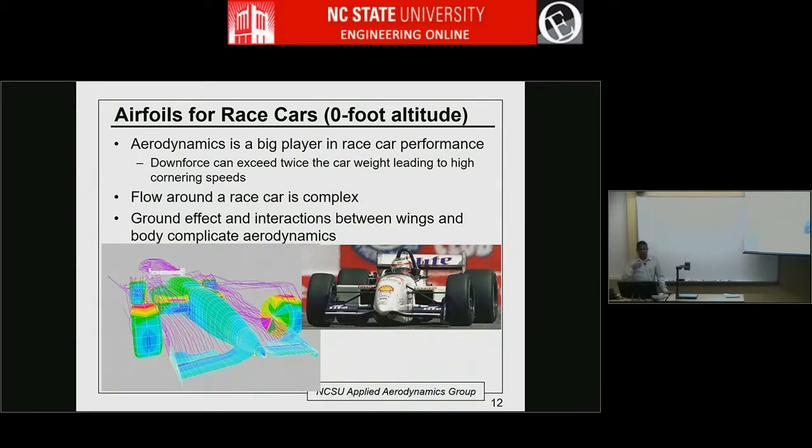That's because on a straight track it doesn't matter, but once the race car has to go around a curve, it's all friction that keeps it on the track, and the faster you go, the more friction you need, and more friction means more downforce. Downforce always helps. So many of these race cars produce something like 3 plus times the weight of the car in downforce.